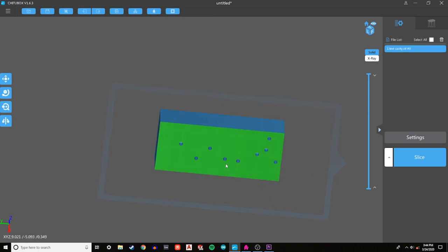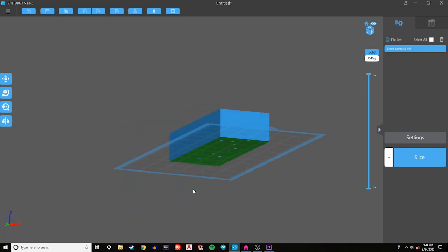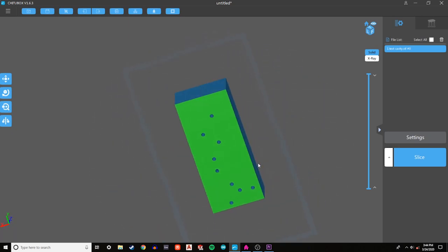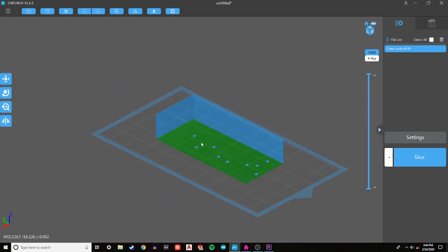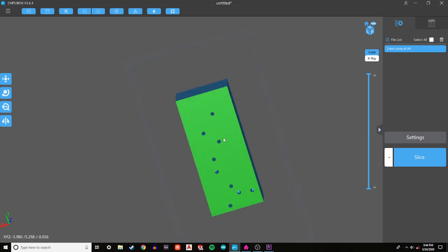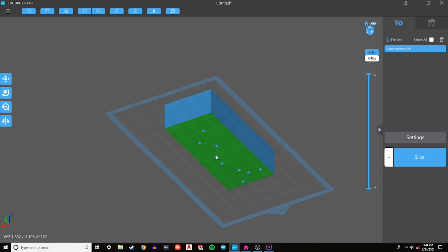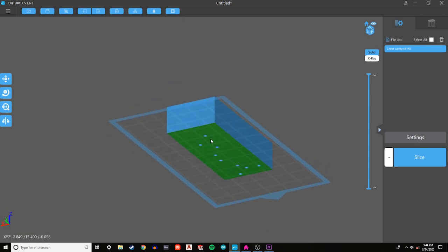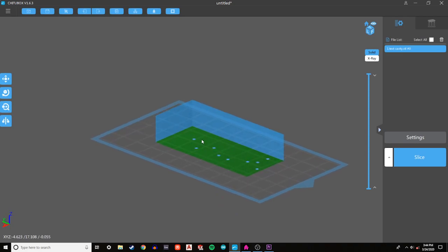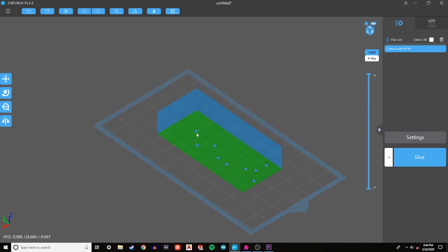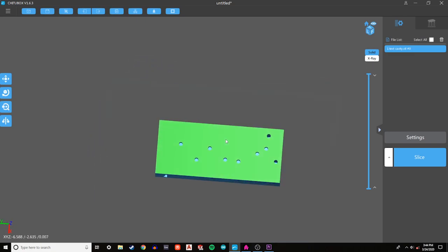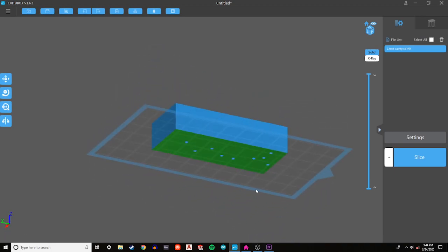And so when I set these up, after I give them their alcohol bath and rinse them off, I let them lay. You can go ahead and sand it if you want, but for a while after I'm done with the whole process, I let them just lay on their back or however they're going to drain best, whatever orientation that may be, just because you're going to see the liquid coming out of these holes for quite some time as it slowly drains out of there. And for me, it's probably slower because my holes are so small, so hopefully you guys are going to use some more appropriately sized drainage holes and it's going to work out a lot better for you.